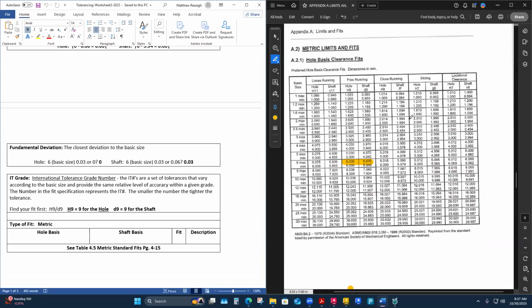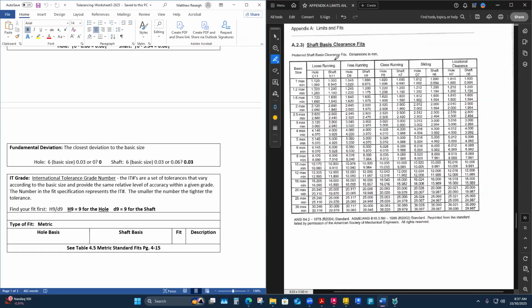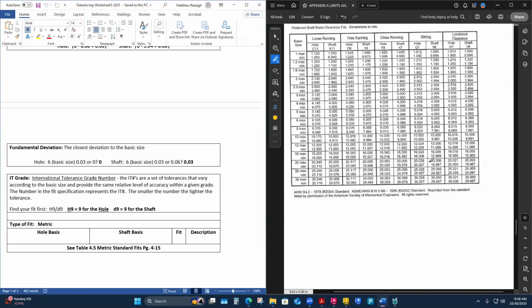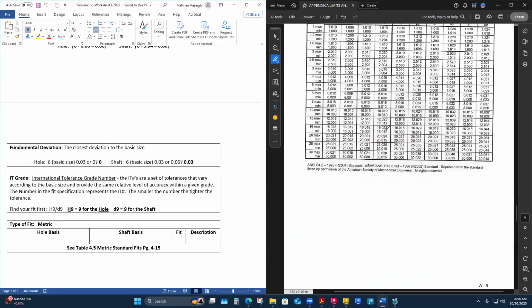And so it's got the capital letter. And it could be that it's like this is a hole basis. So let me look. I just want to double check myself that maybe it's capitalized because it's hole basis and that's the preference. But let me look at one that's shaft basis. I think it still maintains that relationship. If you see a capital, that's the hole designation. This lowercase is shaft designation. And I think it's just that the metric system, whenever they decided to have a shorthand classification of fit code, that's how they coded it. Yeah. You'll see that's common in all these columns. Yep. That's a good question, though.